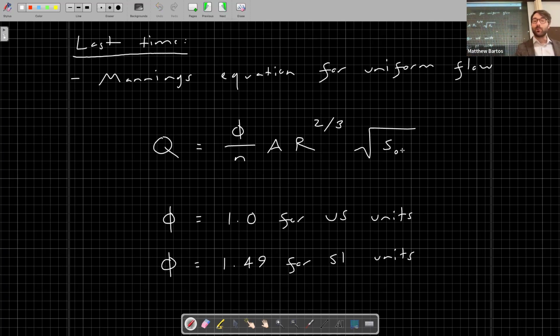So it takes the form of this equation here, usually with discharge as the dependent variable. So Q here is our discharge, and it's relating that discharge to the depth of water in the channel and the hydraulic geometry that that depth defines. So we have the discharge as our dependent variable. This S naught, this is the bottom slope. This is something that can be measured or surveyed.